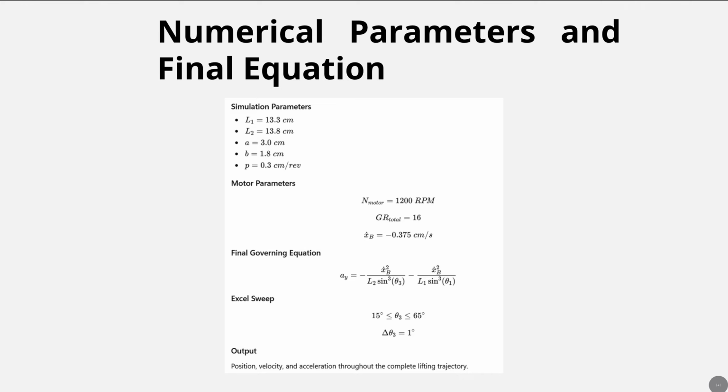This equation was implemented in Excel to evaluate the position, velocity, and acceleration of the scissor jack throughout its complete lifting trajectory. These results provide a complete kinematic description of the mechanism and establish the basis for future dynamic force and power analysis.